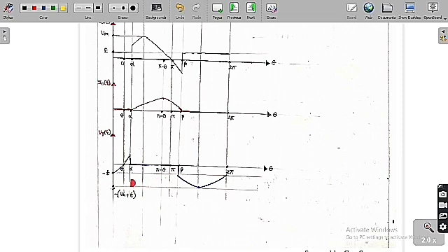A negative voltage occurs across the thyristor in the region of 2 pi minus beta plus theta. For this region, the thyristor is going to experience a negative voltage, which is 2 pi minus beta plus theta. Therefore, the circuit turn-off time is equal to 2 pi minus beta plus theta divided by omega, and the peak inverse voltage of the thyristor is equal to Vm plus E.